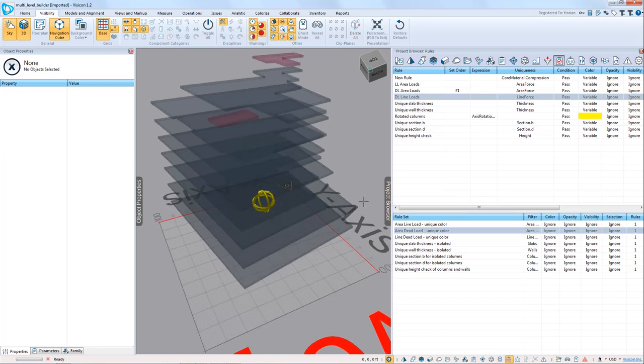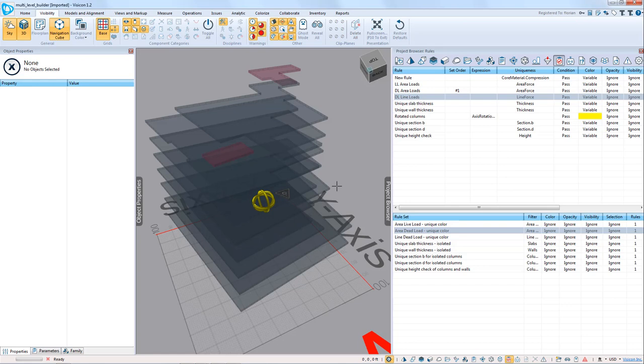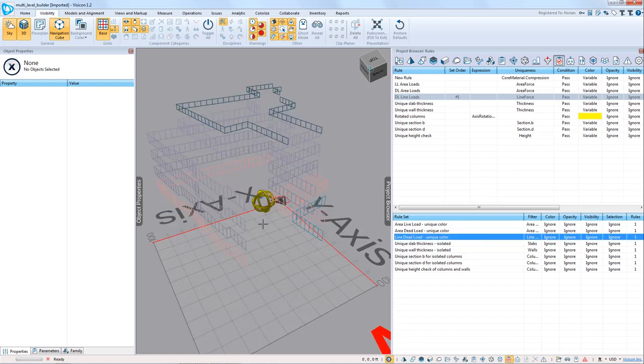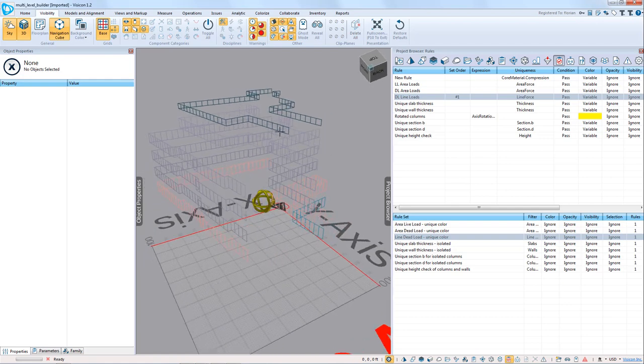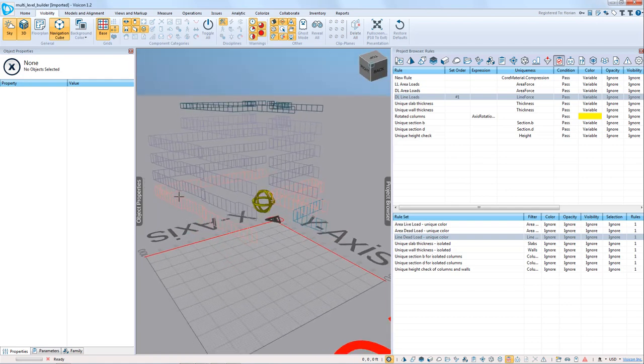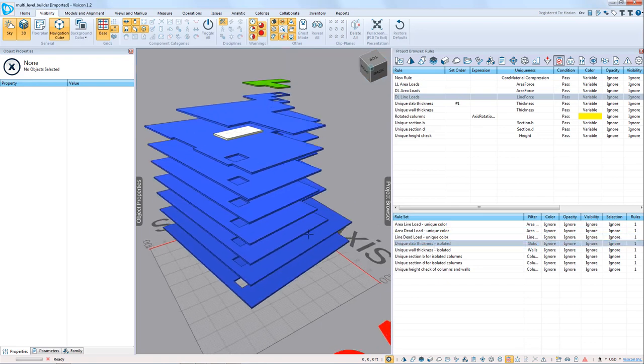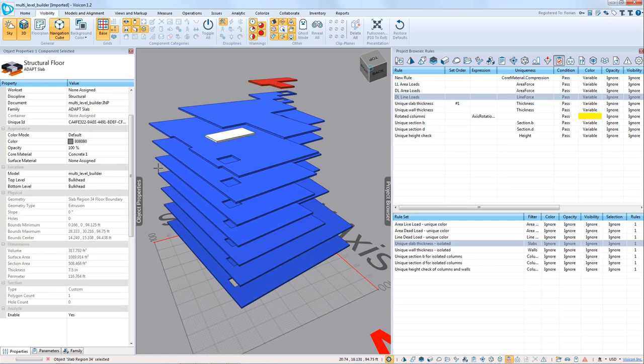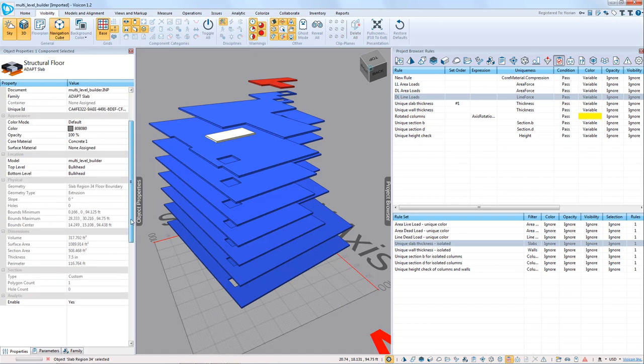We're going to do the same check for our area dead loads. So here I can see where I have uniform patches. We can do this for our line loads. So again, I can verify, should I have different line load here where it's pink versus blue? We can isolate various slab thicknesses. So here I can see that this is a green load right there, and this is 7.5 inches. This is a 7-inch slab, and all of the blue ones are uniformly 8 inches.